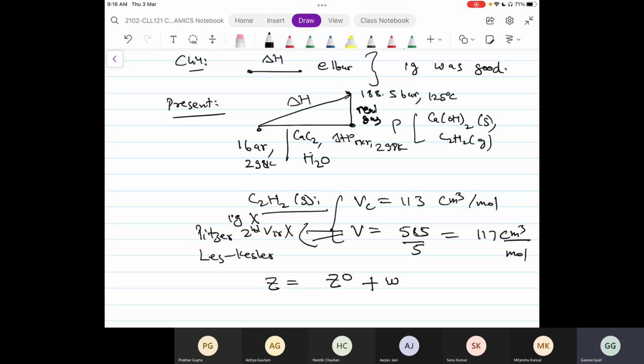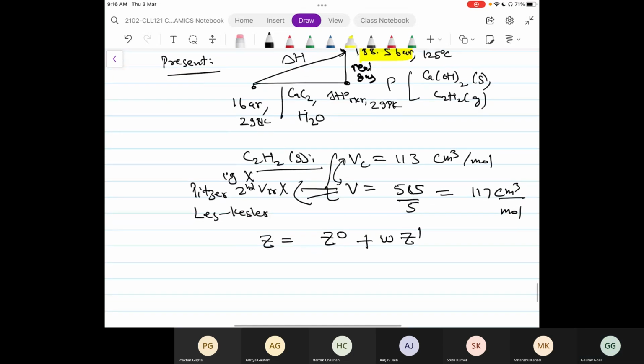And some of the numbers I have written after doing the calculation. Okay. So pressure is not known to me a priori. The reason why I am using Lee-Kesler is not justified on the basis of pressure; that is something I calculated later on. I'm justifying it on the basis of comparison of the actual specific volume to the critical volume. They are very close. Therefore, I am deducing that I cannot use simpler equations of state or simpler correlations. I have to use a more accurate correlation because I will be at high pressure. I don't know what pressure, but high pressure.